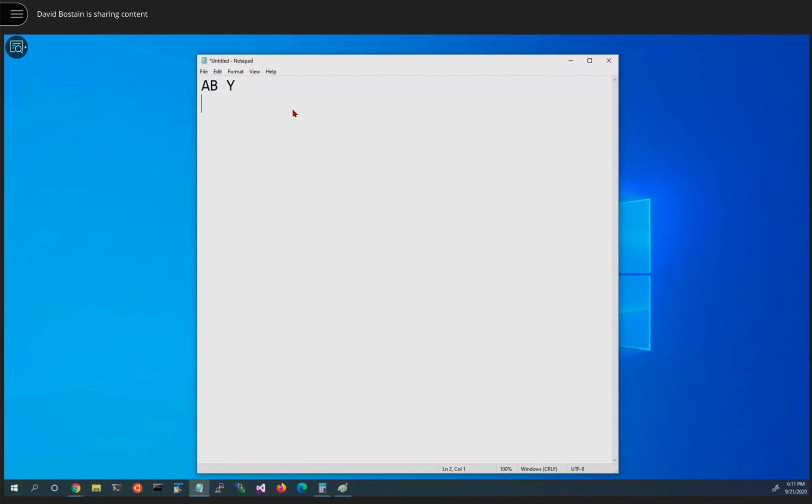And we're going to produce the numbers in our table in normal binary counting sequence. So I would put them in this order naturally. Now, you should be able to see that there are no other possible combinations of 2 inputs. And that leads us to a potential formula. The formula says that the number of lines in the table is equal to 2 raised to the number of inputs.